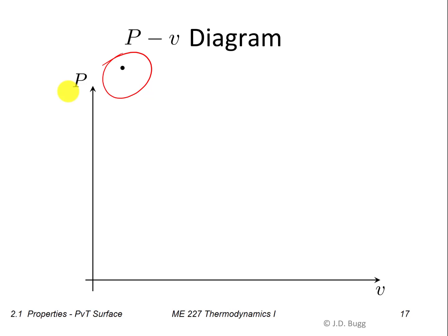So we're starting off with a liquid in that container, and we're going to start to increase the volume. So when we have liquid inside a piston cylinder device and we increase the volume, the pressure drops very rapidly. So the first thing that we would see happen here is a rapid decrease in pressure. So it moves a tiny little bit to the right, but hardly at all.